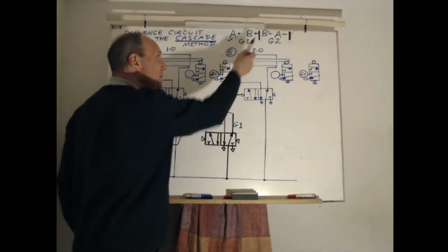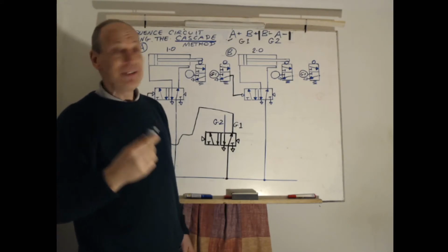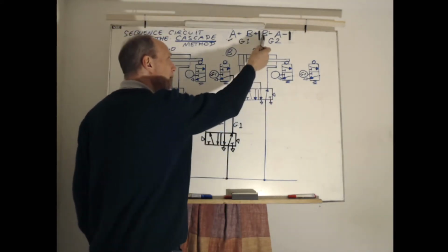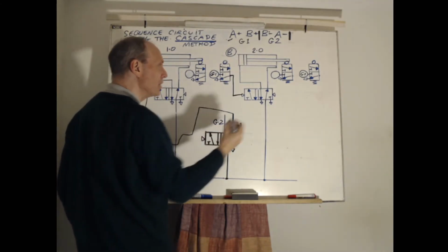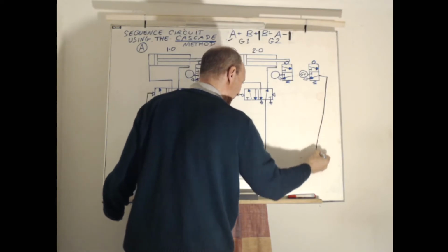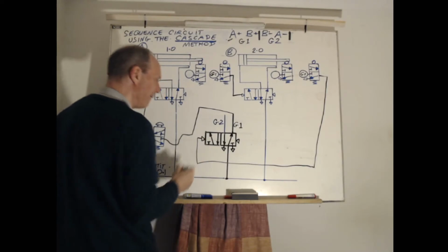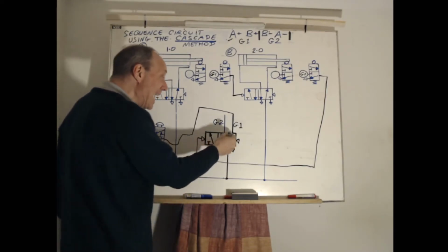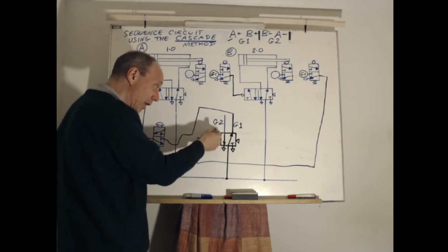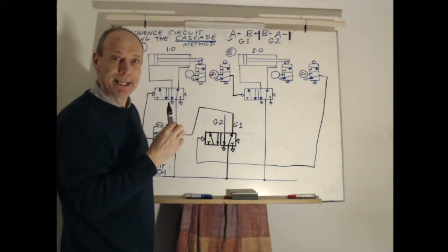However, we've now reached the trapped signal problem. So we need to eliminate G1 and the trapped signal. This valve is not going to be able to ask B minus to take place. What it's going to do is take its signal when B goes B plus and operate this valve, and it's going to effectively send this G1 through this internal line out of the exhaust and depressurize everything and remove the trap signal.